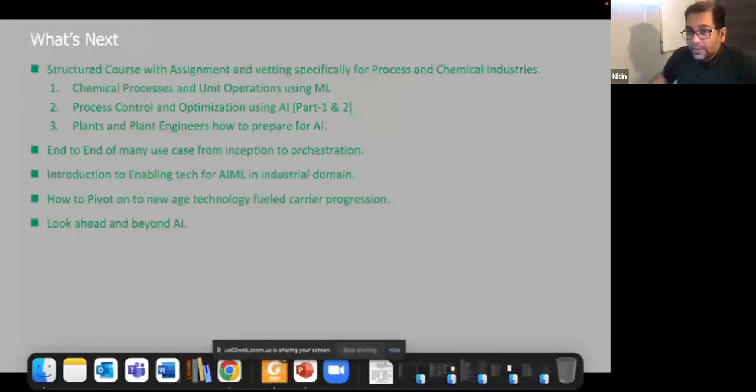That is, first is property-based applications. These are like Aspen, UniSim, HYSYS, and all those. These are property-based applications where you have a database where you understand the binary and tertiary interaction of molecules, estimate the effect of those changes on the physical aspect of those molecules, and predict the outcome. That's one. These are limited to the database, because Aspen Plus does not completely have the whole polymer structure or polymer molecules.